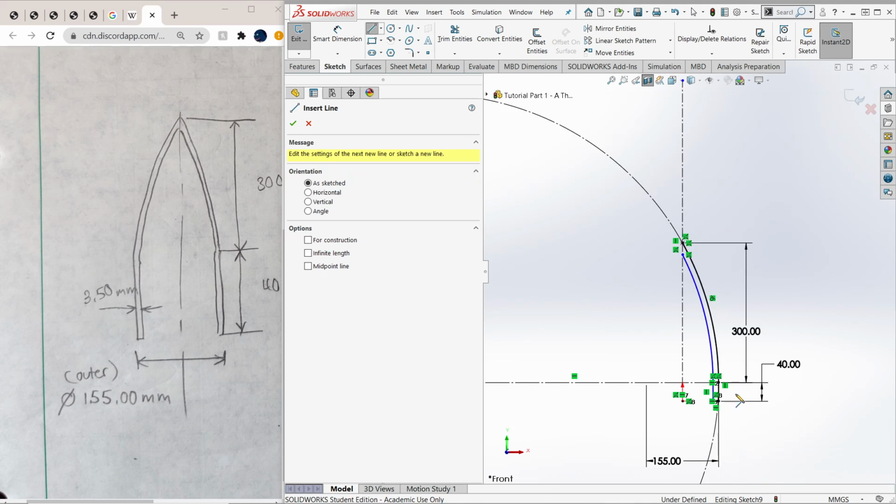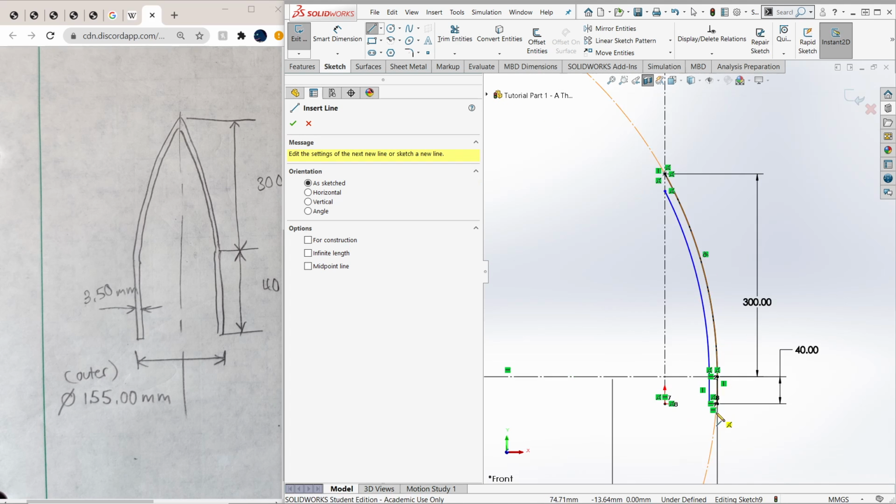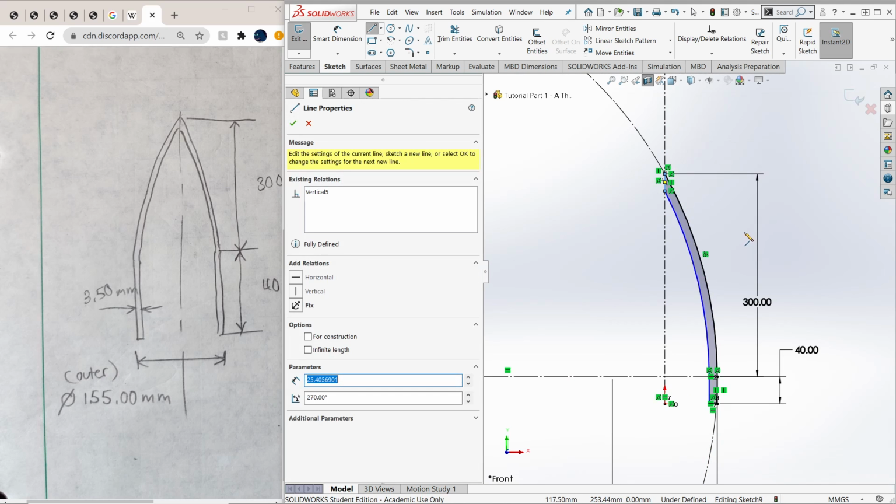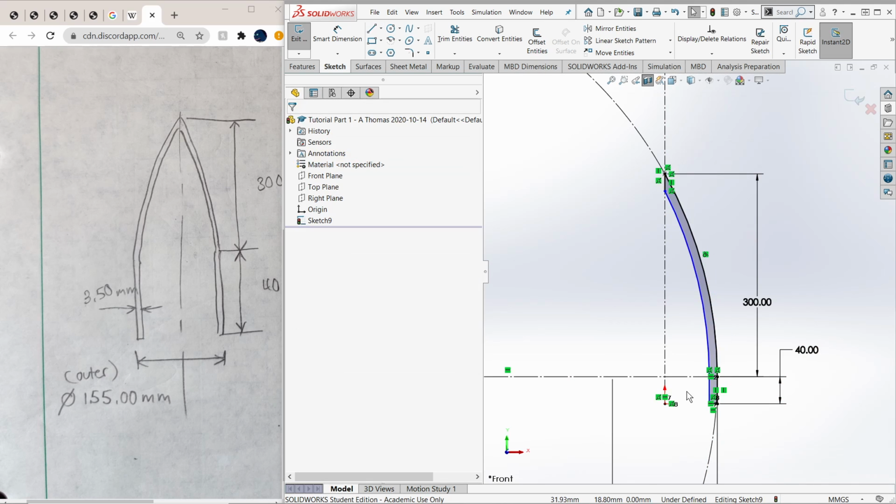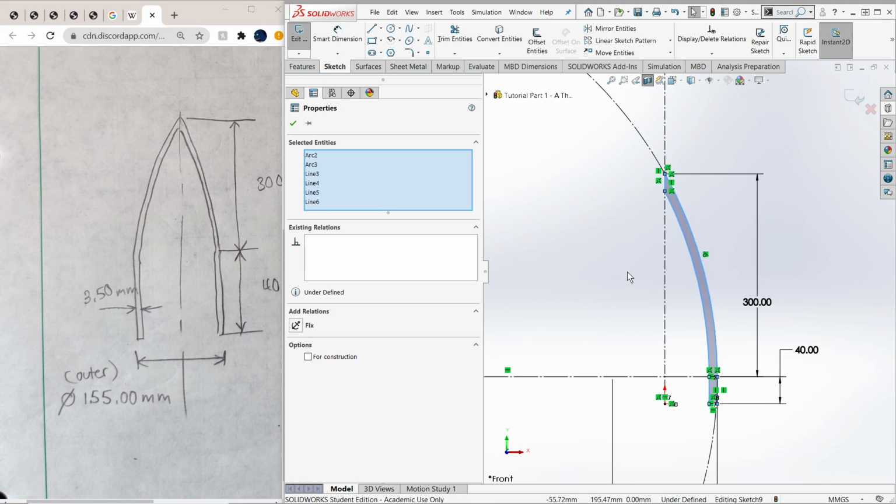If you notice, there's no shading in here. And when I close this, you see how it's a shaded region. When you do an extrude or a revolve or any type of feature, you need to use closed surfaces.